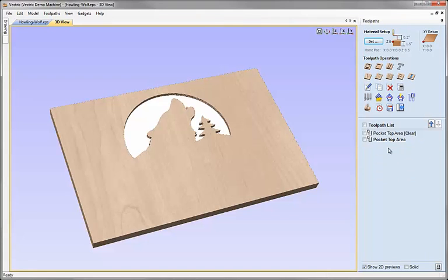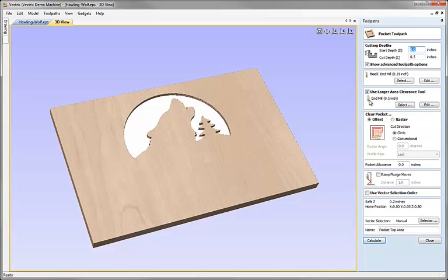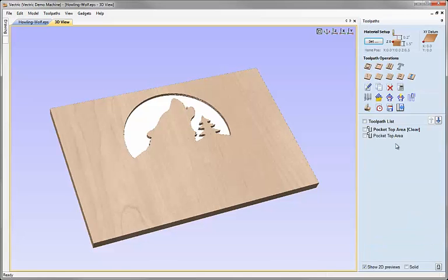Before we move on to the next set of toolpaths, also worth noting that when you've got two toolpaths like this that are essentially linked because they were created with a single operation, if you double click on either one, or you select either one and come up to the Edit Toolpath icon, then it's going to open the form with the information in it, and if you change parameters in here it would recalculate both those toolpaths. You can see that it's still got the information for the 1/4 inch and the 1/2 inch tool, which is why we've got two toolpaths generated from that operation.